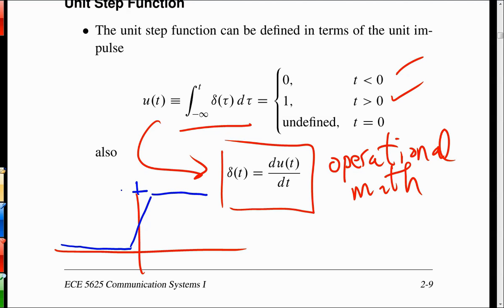This is even pretty idealized. And it would be going through approximately 1/2 right at 0. But that's even pretty idealized, that straight line piecewise approximation. If you were to do this in the lab with a square wave generator and zoom in on the rising edge of the square wave, you're actually going to see some rounded edges on there, right? And most good pulse generators have a knob that you can use to control the rise and the fall time. You can actually slow the edge down if you want to.